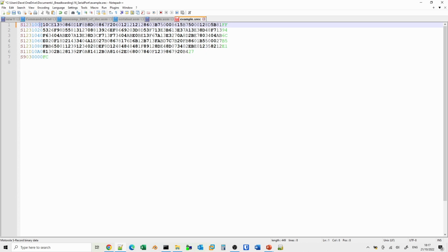And if we were to go in and change any byte values, so if I just change the first byte from 0 to 1, for example, and go to the next line, you can see that it's now telling me that the checksum is incorrect for that row. So if we change it back, and we change one of the addresses as well, you'll get an invalid one. And if you change the checksum itself, again, it will show as invalid. So it's quite a useful thing. If you open this in Notepad++, we can check that it's okay.